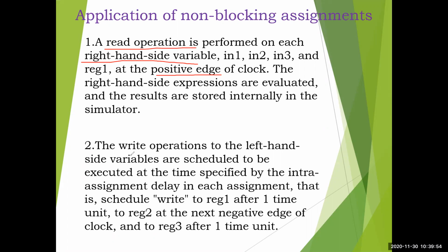In a temporary variable. Then write operations to the left hand side variables are scheduled based on the delay, to be executed at the time specified by the intra-assignment delay in each assignment. That is, schedule a write to register 1 after 1 time unit, register 2 at the next negative edge of the clock, and register 3 after 1 time unit. Accordingly, this will be executed.